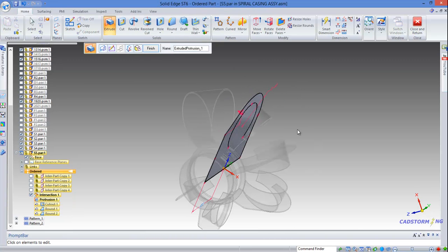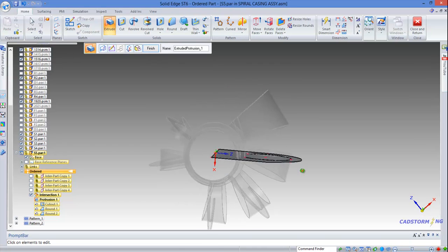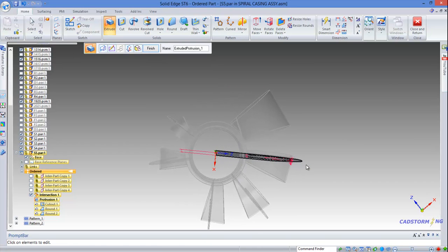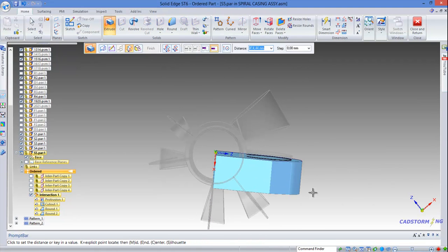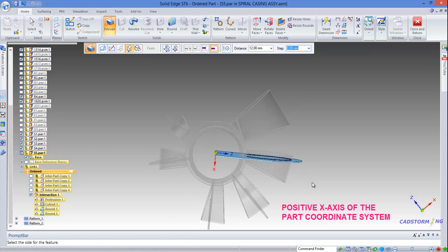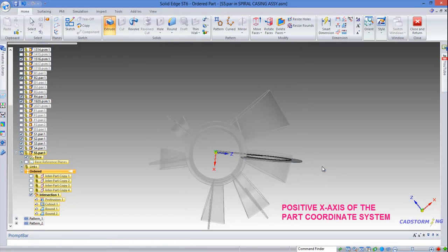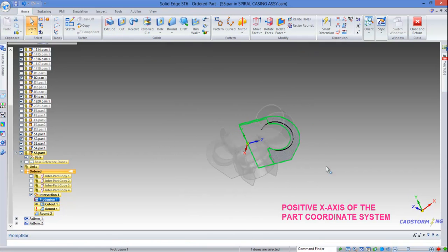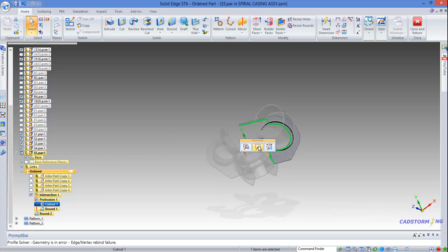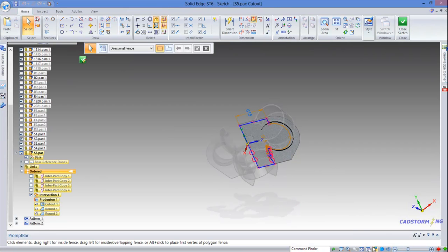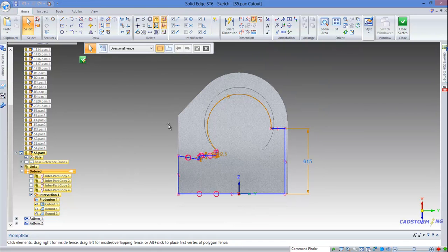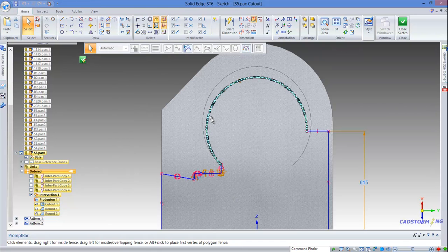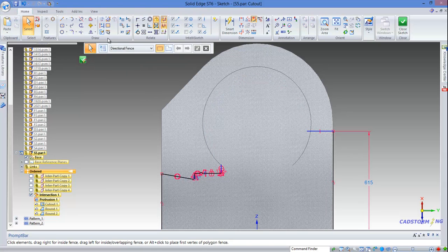Now Control Q, and we make sure that the extrude is in this direction, so not symmetrical this time, this direction 12, and OK, and we can proceed for the cut. Number 2, and Control Q, remove this one.